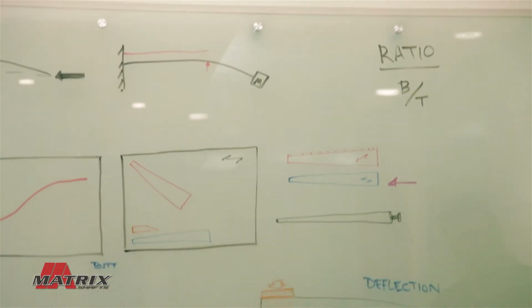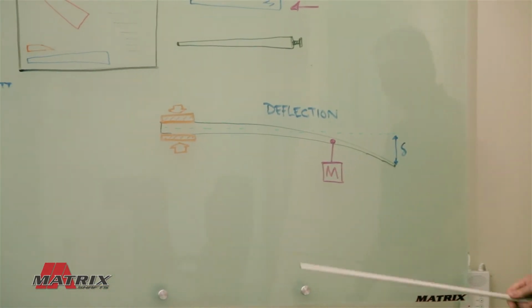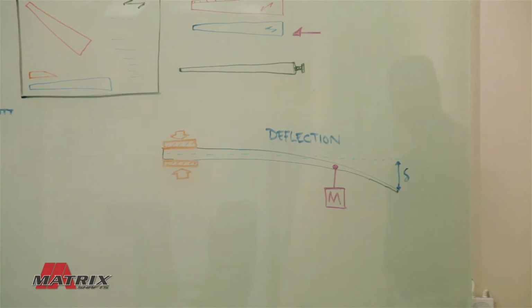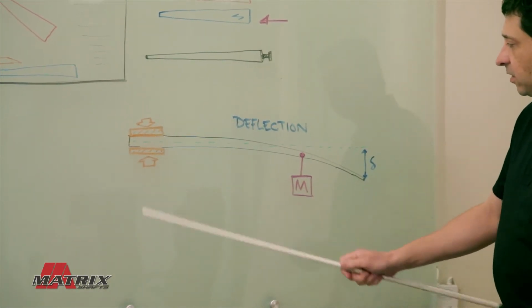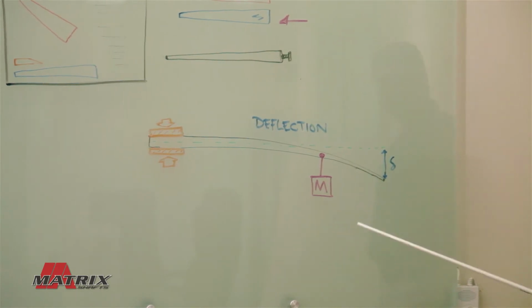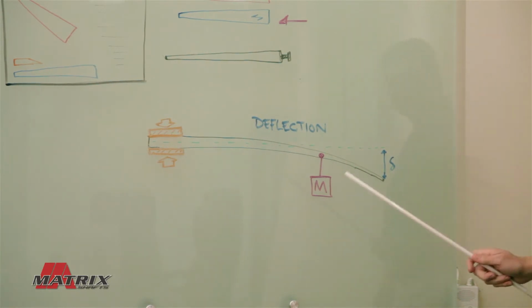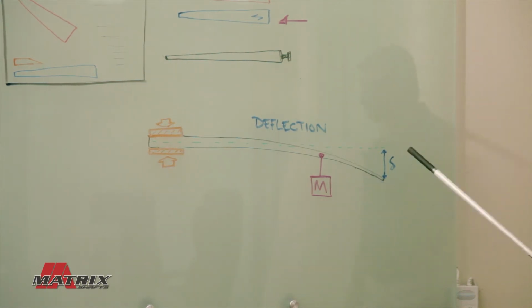And this diagram down here shows a tip or butt deflection setup. You have your shaft in here, clamped on one end. You have a mass to deflect the shaft. And then from the opposite end of the shaft, you can measure your deflection from the horizontal. A lot of companies will put one or both of these tip and butt deflections to describe their shafts and to distinguish them between family lines.